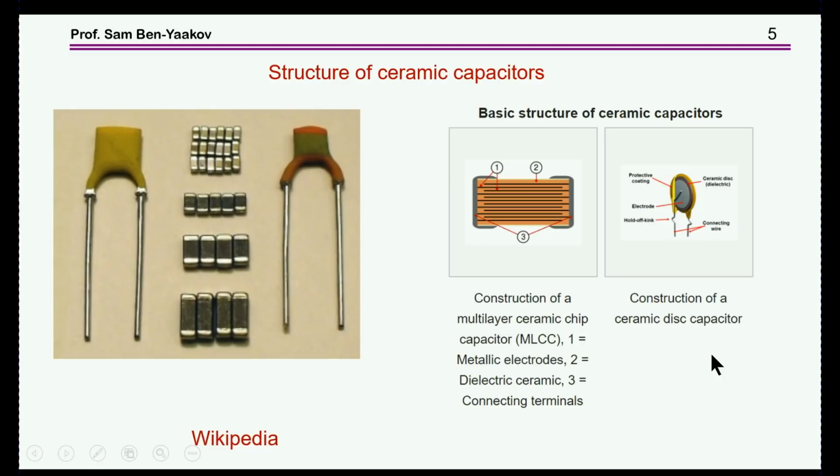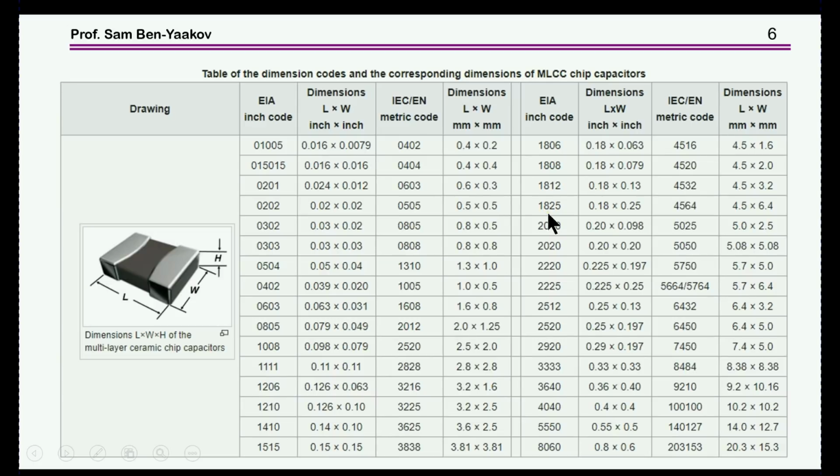So we're all familiar with ceramic capacitors. They are very famous and very, very useful, and also due to the fairly low price, they are used a lot, in just any design. We know the through-hole, the SMD, and of course the multilayer ceramic capacitor, in which we have a comb type of arrangement in order to increase the surface area and also to reduce the inductance, as a matter of fact. So these are the capacitors I'm talking about.